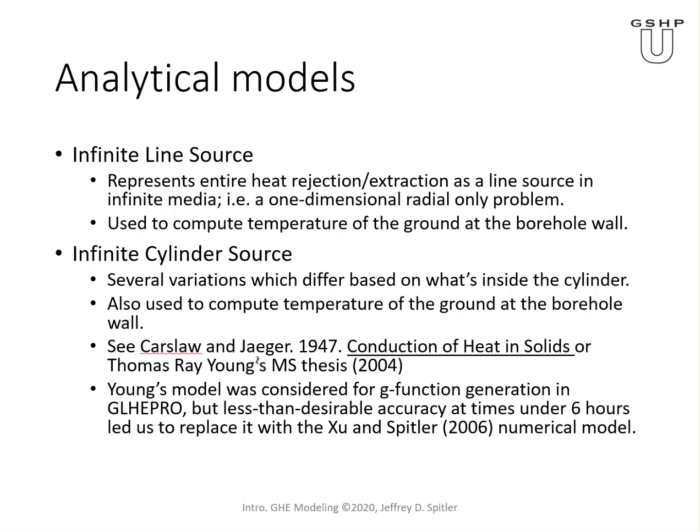Ray Young was one of my master's students. He developed something called the buried electrical cable model, which is how Carslaw and Jaeger originally envisioned it. So the material inside the borehole was different, and there was also a resistance, one or two resistances, now I've forgotten. We actually looked at using it, but it tended to have a bit low accuracy under 6 hours in time. So that's when we came up with GLHEPro and Spitler, which has a 1D numerical model inside the borehole used to generate the short time portion of the G function. The G function is a response factor that we'll talk about later.